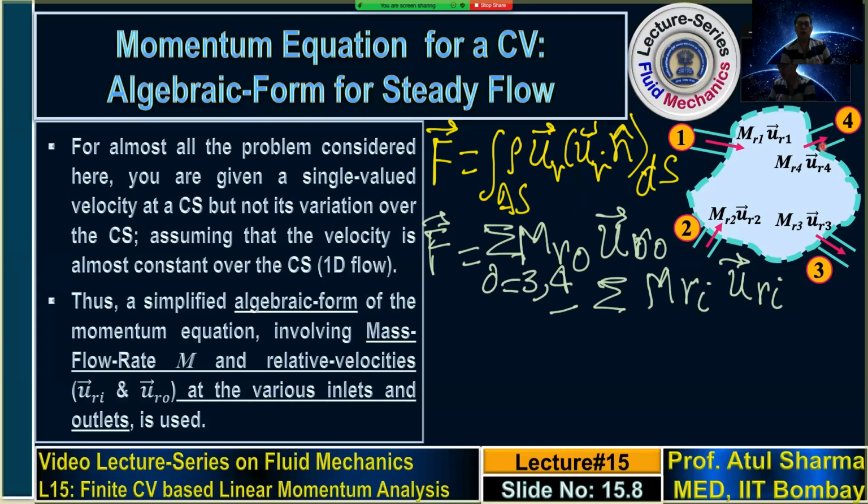Now, as you might have studied in your earlier course on fluid statics, whenever we apply any vector equation, we apply it component by component. So for a 2D case in a Cartesian coordinate system, let us write down the x component and y component. To write down the x component, we will write the x component of the velocity, which is the horizontal velocity, and that I will represent as small u, and to obtain the vertical component Fy, we will here have the v velocity.